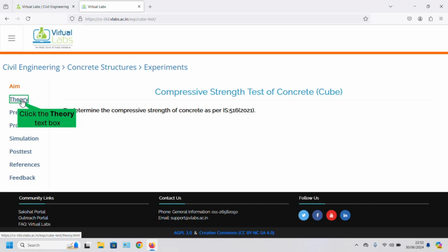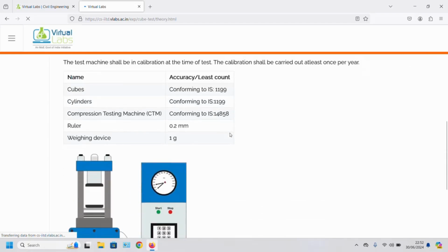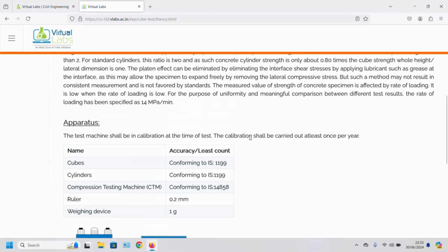Basically, those who are engineers will understand that when you want to test the strength of concrete, you can create cubes that you cure, then you crush them to see whether the concrete mixture is well done and is conforming to set out standards.